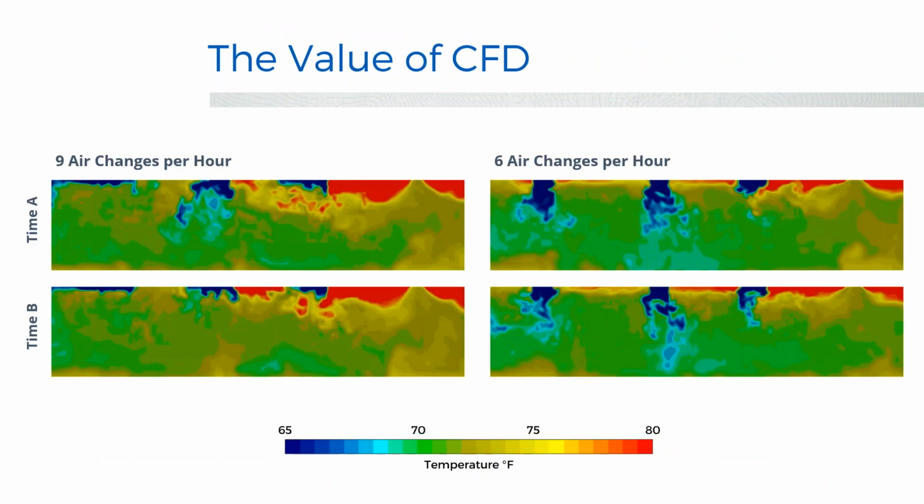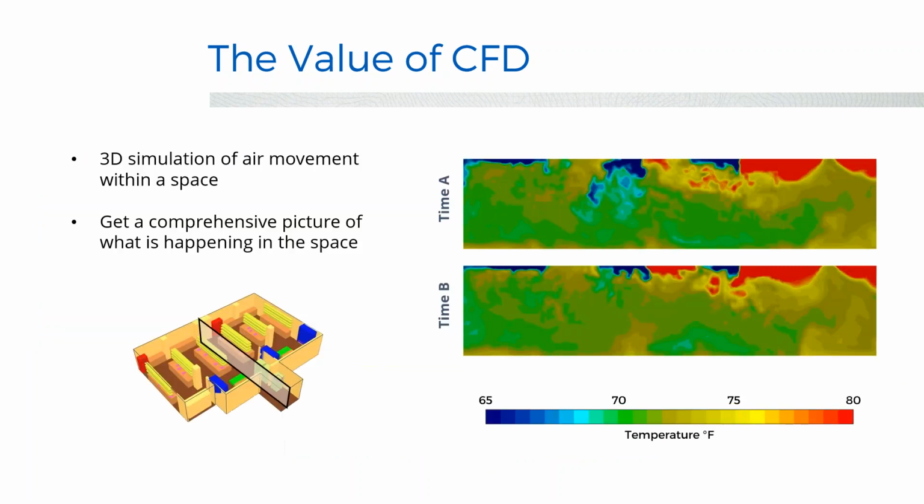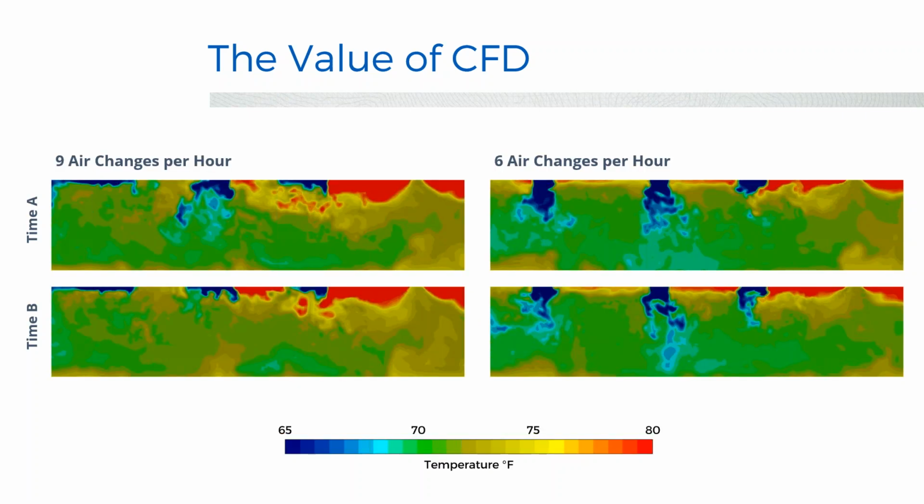So for these ones, if that's what they're talking about, it was a turbulent flow. We were running LES, or not LES, sorry, FDS, which is LES. So Fire Dynamics Simulator has a fairly robust LES solver. You can see in this lab, the geometry was very blocky, so everything was kind of squares, which makes it an ideal candidate to run with LES. And you do get the benefit of the turbulent mixing, which for a lot of things is very important. It also provides good entrainment modeling, which is the downside of a lot of steady state simulations. You won't get the mixing of air on your diffuser jets. You tend to get a very smooth jet into the space instead of modeling this mixing. So yeah, turbulent. Okay, great.